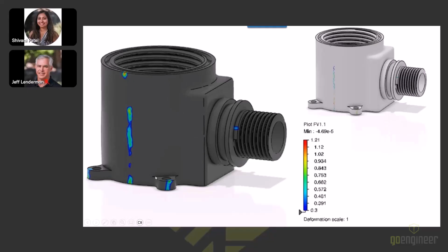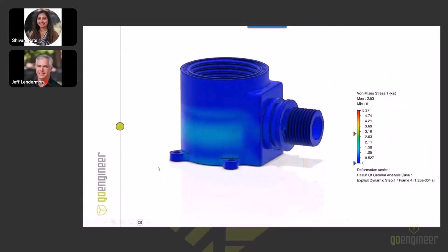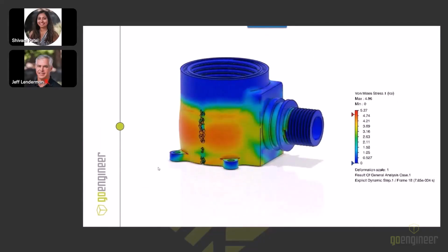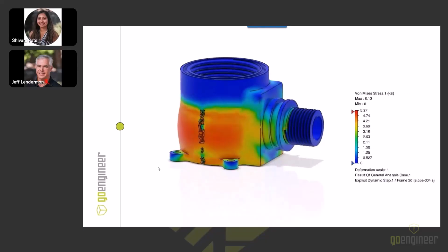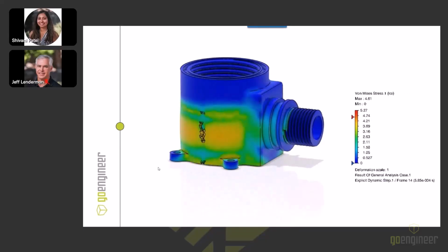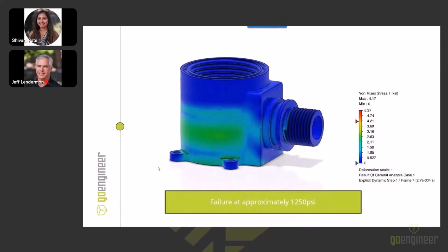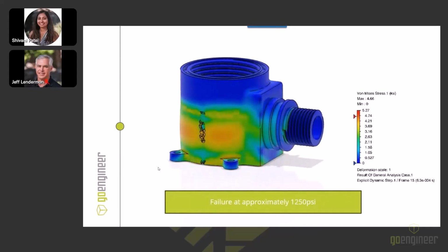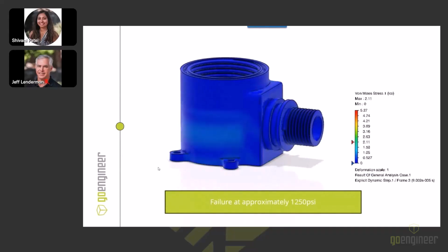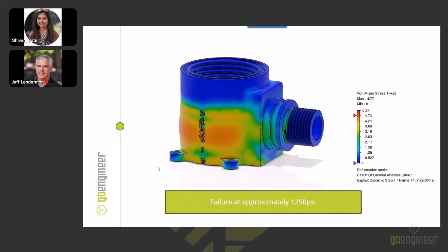All right. So once I put in that little bit of damage modeling, and those field variables and the material properties, that's enough to get this running. So I did go ahead and give that a run, applying that pressure, and with that damage model, we see elements delete as that particular fracture strain is obtained. So we get to about 1250 psi before we start seeing those elements begin to delete. So a little bit into the plastic portion of that curve. And so we see a crack essentially, and what would be failure in the field, right?